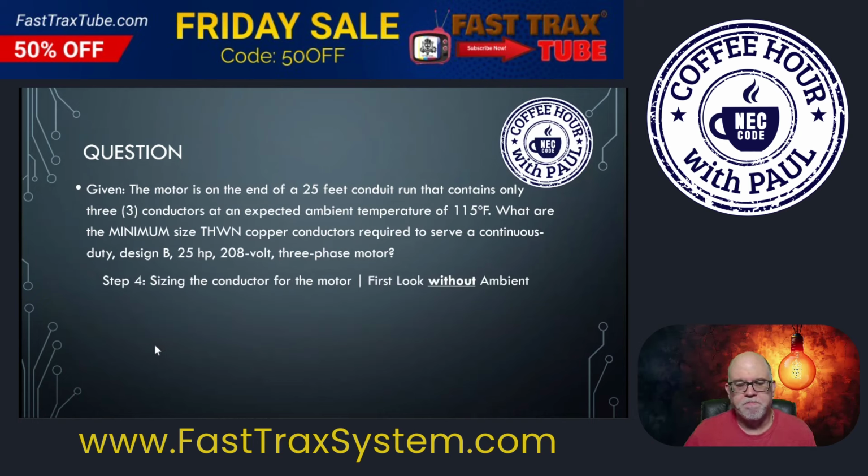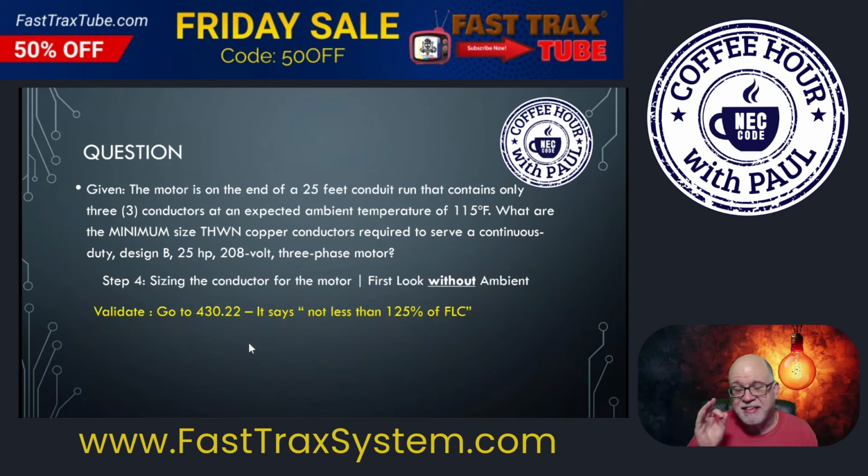All right, so first thing we want to do is, what if we were looking for the conductor? Now, this is typically what you get on an exam, right? If they don't give you the ambient. I'm going to show you how this can differ in conductor sizing. If they don't give you the ambient, then it's pretty straightforward, right? You take the FLC and you multiply it by 125% because that's what it says in 430.22. Pretty straightforward, right? And it also says not less than 125% of the FLC. Could it be higher? Yes, it could be higher, but it's not to be less than 125%. That's what it says in 430.22.